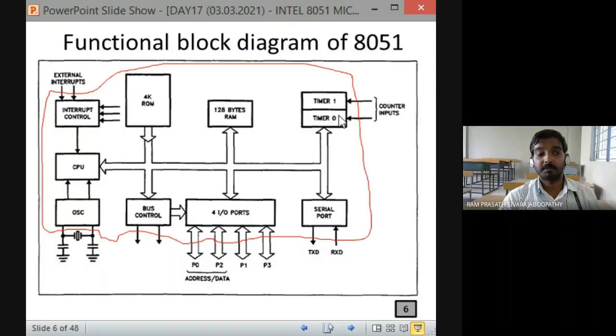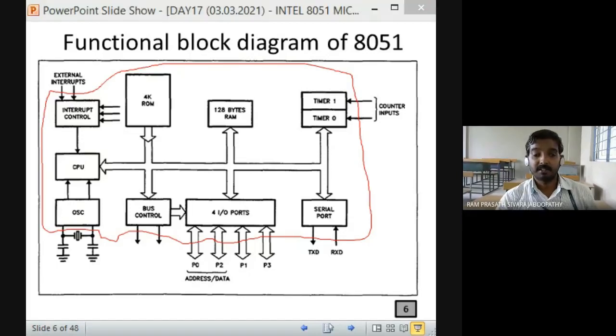In the case of timer/counters, we can say timer 0, timer 1, correct? In the case of ports, you can have P0, P1, P2, P3. Each port is going to have 8 pins, and the pins are named like this: P0.0. Yes, you can see the chat.